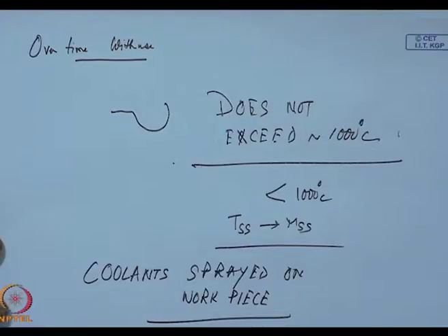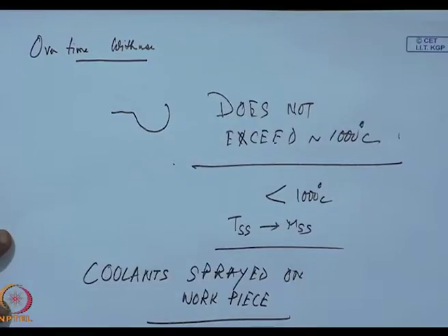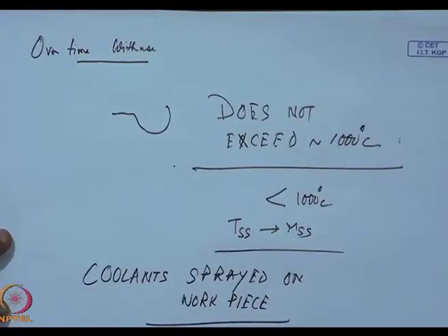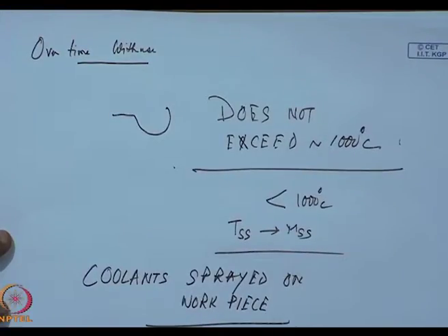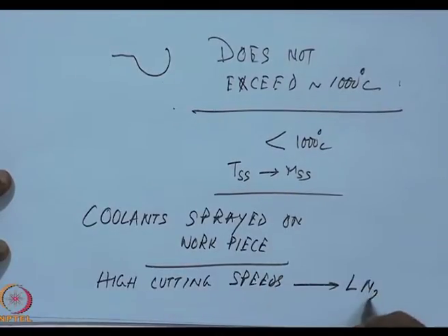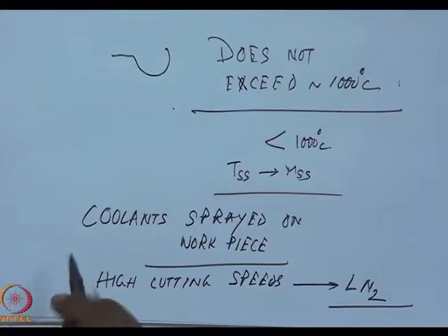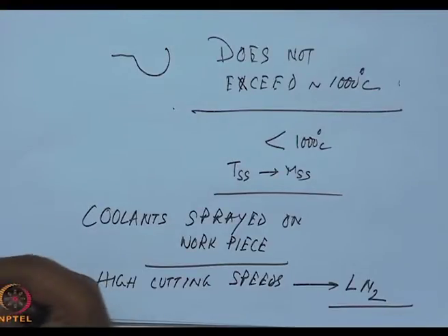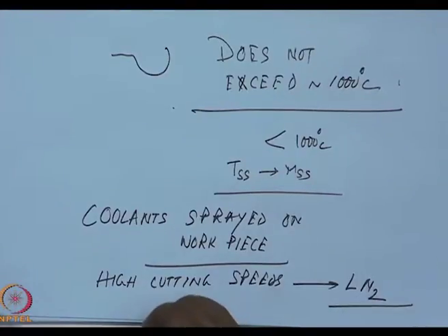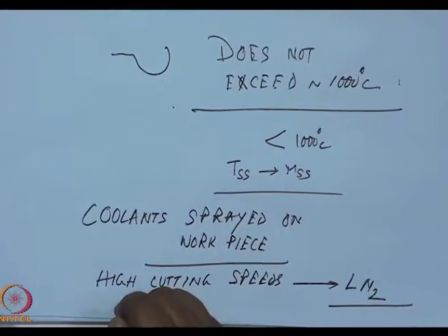At times at very high cutting speeds, we may have to use even liquid nitrogen to cool the whole thing to ensure that the temperature at the tip does not go above 1000 degrees centigrade.